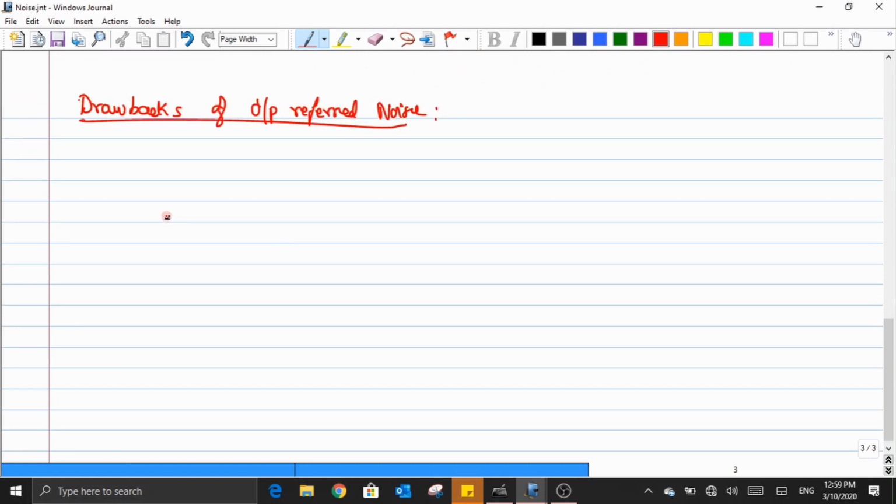Okay, so now let us consider that we have a CS amplifier with V in, and there is a V out, and we call this V out as V out 1. That is being connected to one more stage with a gain of A2, and this A2 amplifier is noiseless. And we have already computed what is the noise coming out of this first stage, that is our CS amplifier. So what was that quantity? Yeah, it is nothing but SV of out.